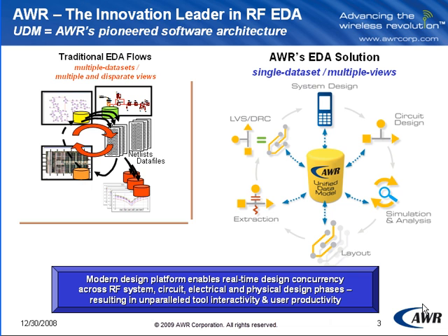So not only can you co-simulate HBT, PHEMT, silicon, module at the circuit or system level, but you can also co-layout, co-verify. You can look at the design in its constituent parts or as one integrated whole. And this really allows you to design within the context of the entire module, not just the bits and pieces. At the layout level, we don't need to reduce our die to pretty picture GDS2 rep cells. We can actually reach down into those die and manipulate them in the context of the overall design. So we can make trade-offs that are very key in terms of space, cost, as well as electrical performance.